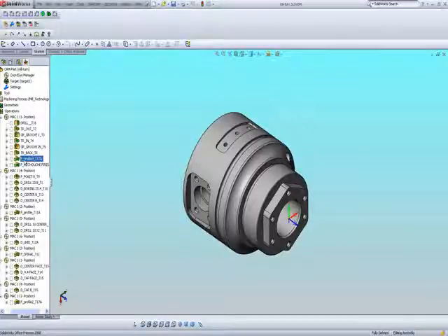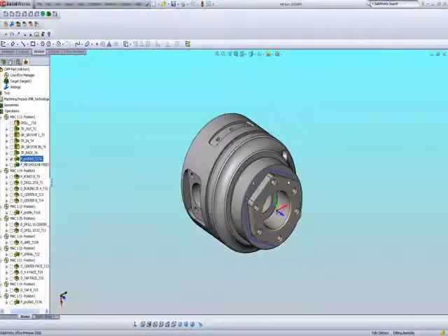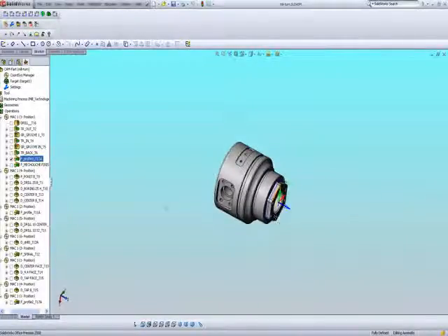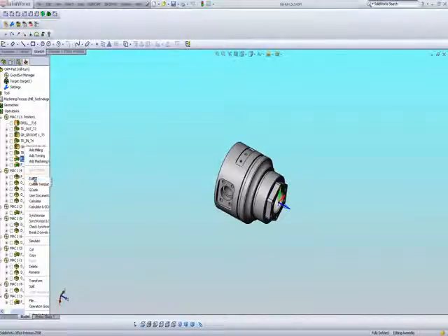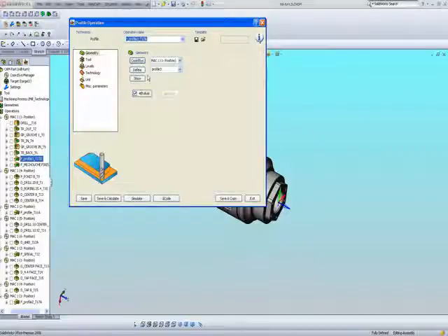Now you'll note when I do my next milling operation, I'm still using the exact same Mach 1, position 1 as I did in the turning. In other words, I do not have to create a specific Mach position for the turning. What I've done here is actually work around the outside of this area over here. It's a simple milling operation where I have, as I showed you, my Mach 1 position 1,